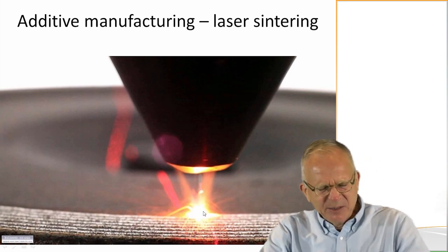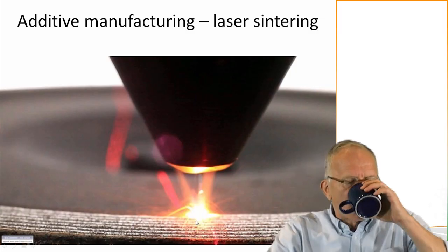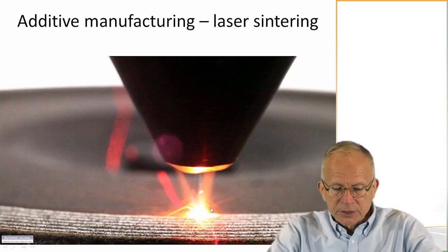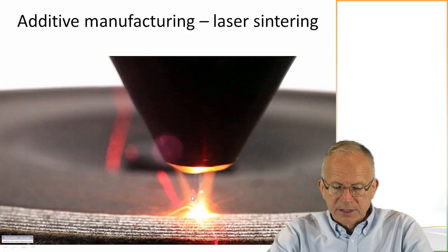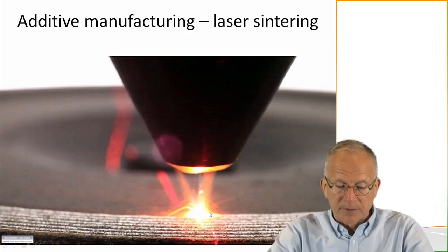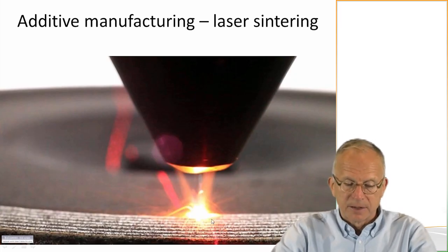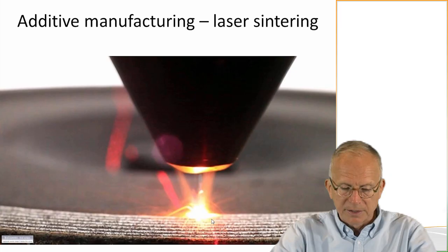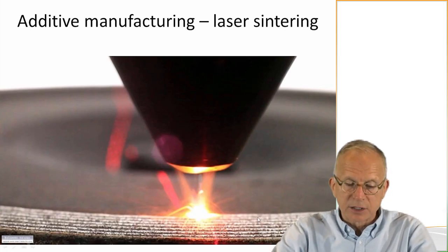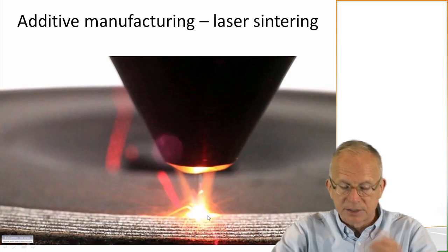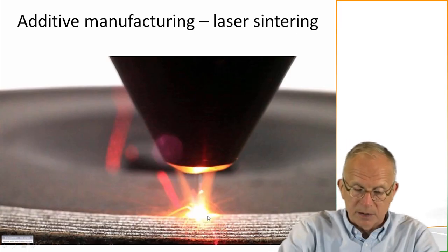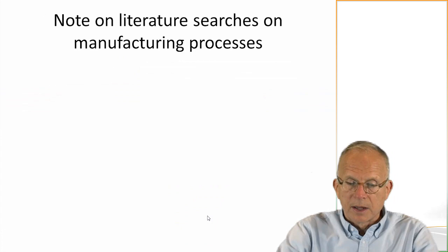Now, one of the issues that we'll discuss in more detail later is that this is warming up the material here, heating it up enough to melt. So the adjacent material is seeing some heat process or some thermal processing, which is sort of a consequence of getting the material near it to sinter and not always perhaps desirable.